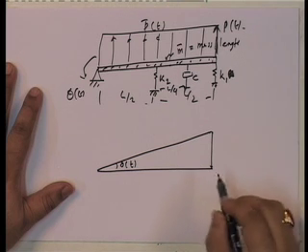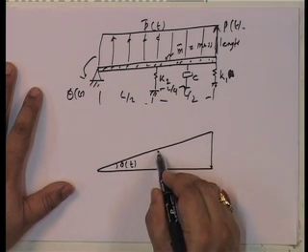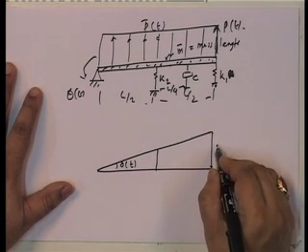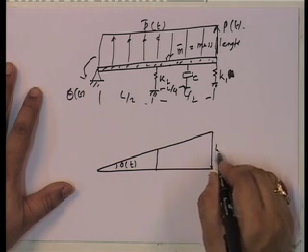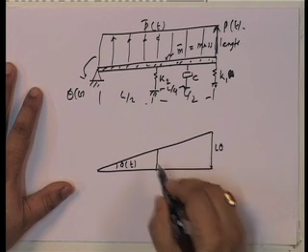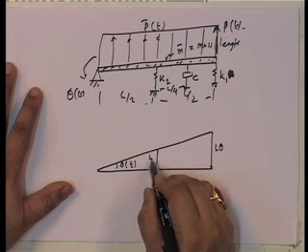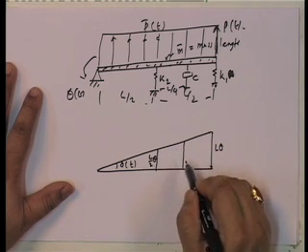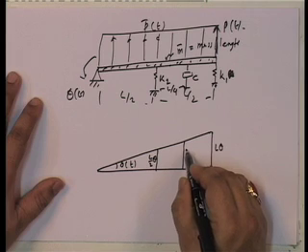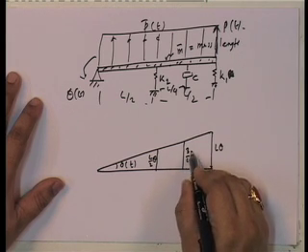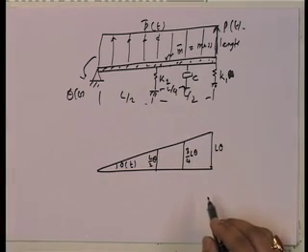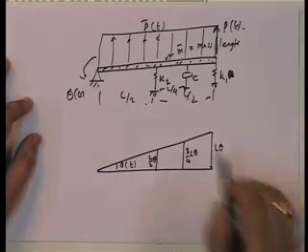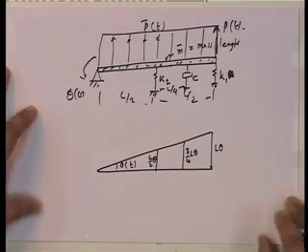So I need to find out all these values. At this point, the displacement is L theta. This is L by 2 theta. This point where the dashpot is equal to 3/4 L theta, and I think that is all. These are the only three point values, everything else is UDL.